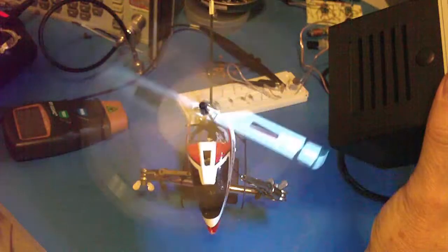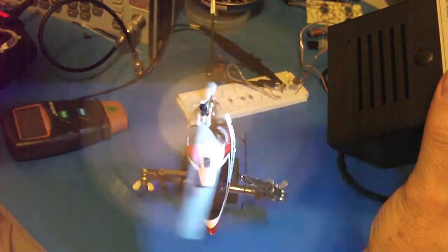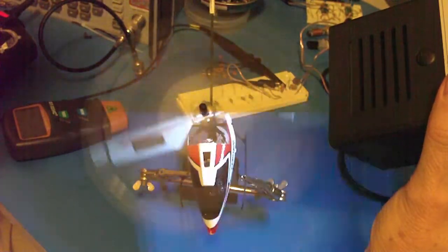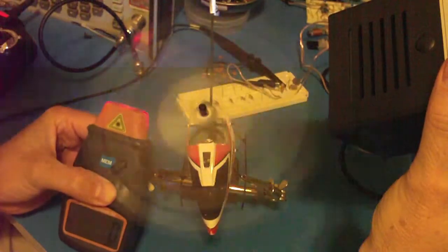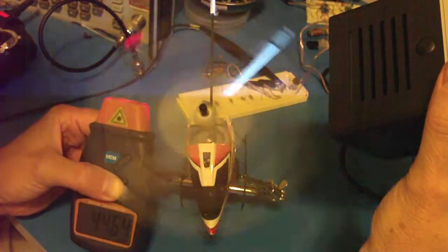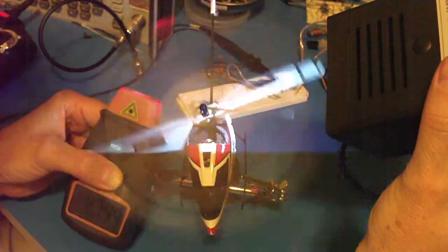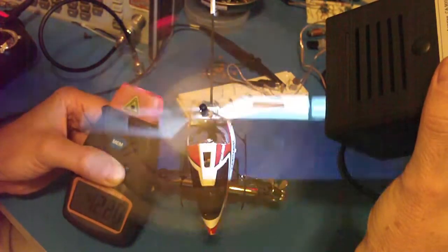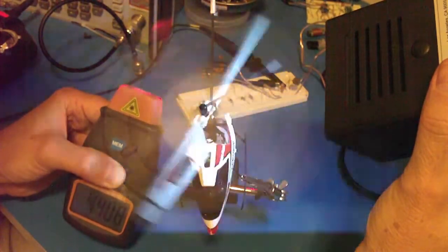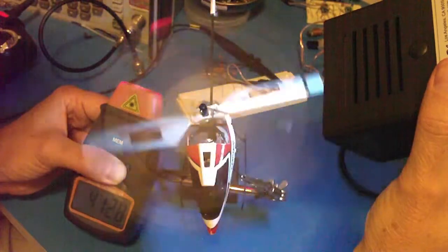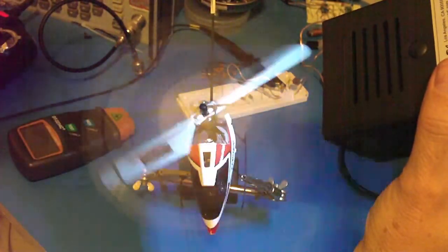So if we try and speed it up a little bit, we're going to go up to, now we see a reflector on only one blade. So this is 3 rotations per sample, which should give us a reading of 4500 RPM. 4450 we just saw, and that's why it looks like it's rotating backwards a little bit. 4456. The faster it spins, the noisier the reading gets. 4408, but a little bit less than 4450. That looks reasonable.